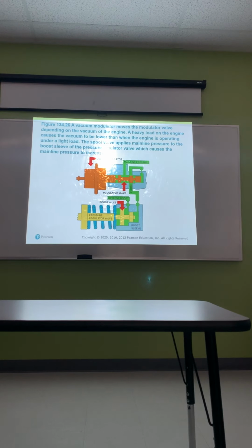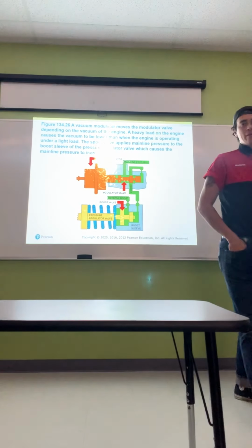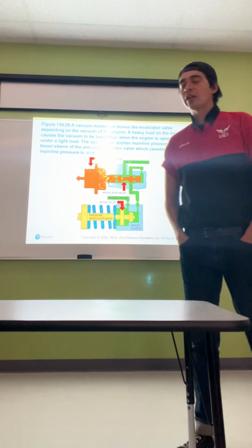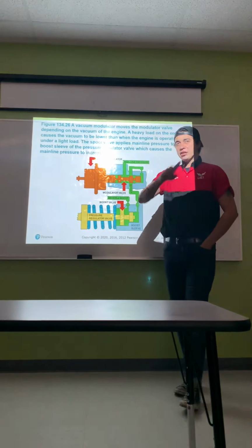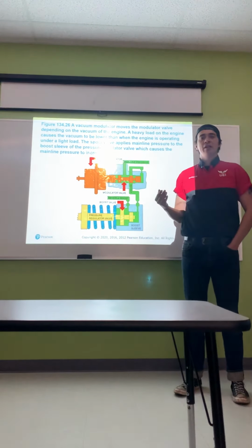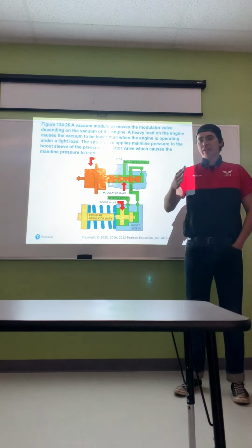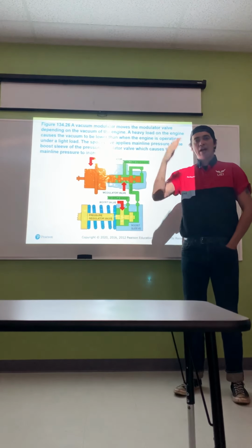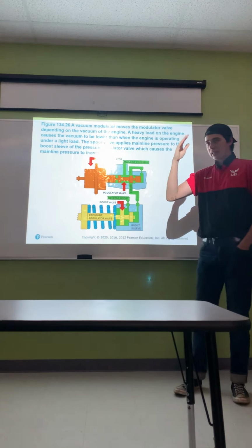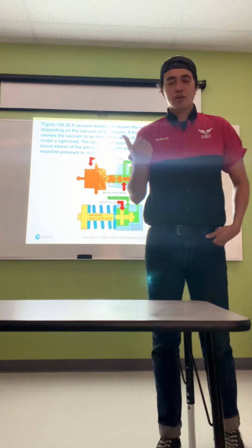Oh, okay, so when you are under heavy load, it doesn't want to shift the vehicle. The reason why is, let's say you're at a nice higher RPM, but under a real heavy load, pulling a trailer up a hill. The last thing you want to do is shift into the next gear, because remember, when you're accelerating, it's more for top speed. Higher RPM in a lower gear is meant for towing. That's why when you're driving with a trailer, you want to turn your overdrive off.